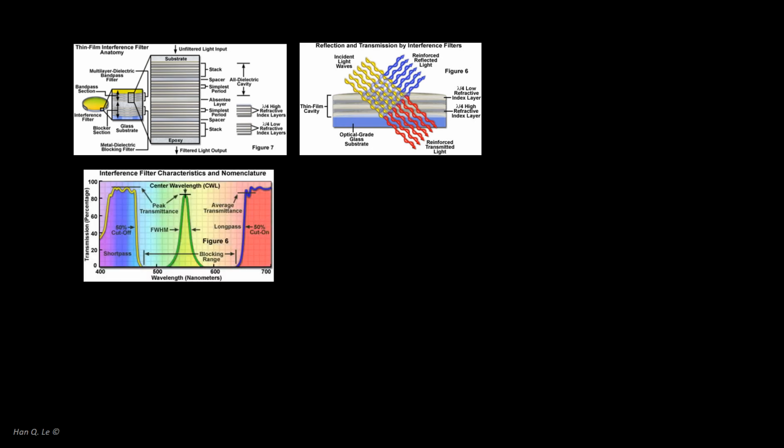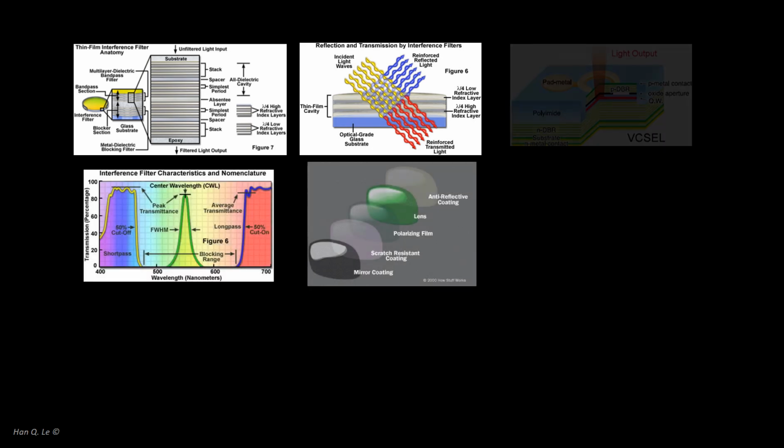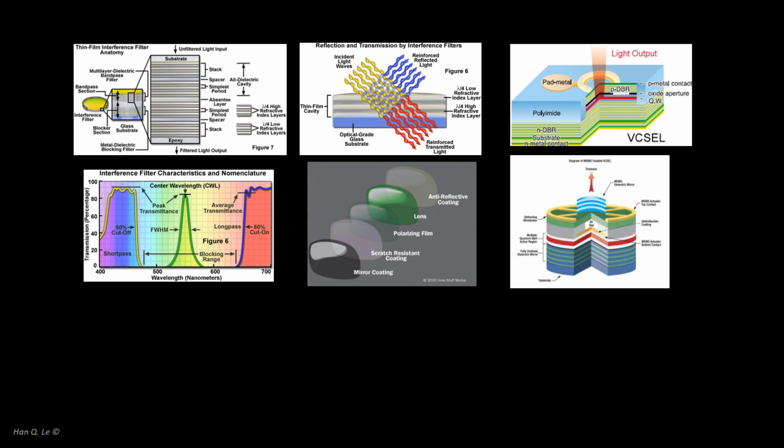For thin film filters, dielectric mirrors, or optical resonators, including passive filters or vertical cavity surface emitting lasers, the structures are designed to engineer light behavior for propagation through the layers with any incident angle, similarly to the configuration studied here. It can be as simple as a single or few layers for anti-reflection coatings on common eyeglasses, or it can be complex multiple coupled cavity structures for narrowband, flat top, low ripple filters for optical communications.